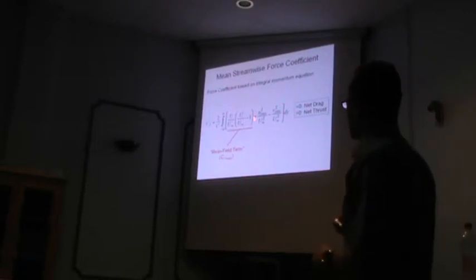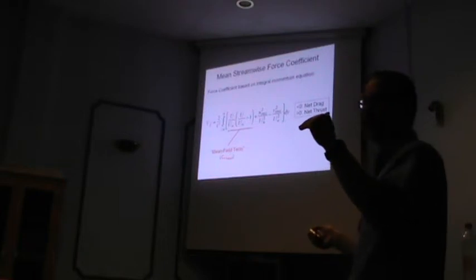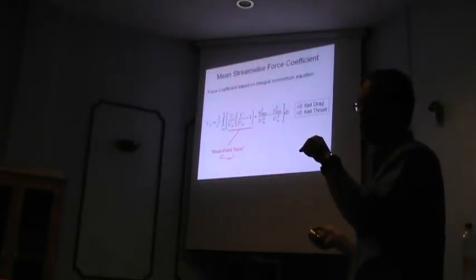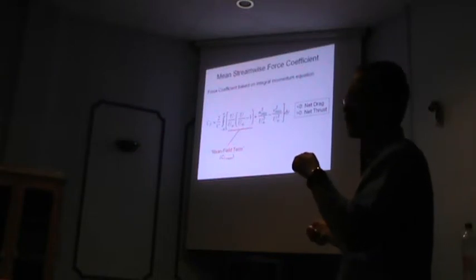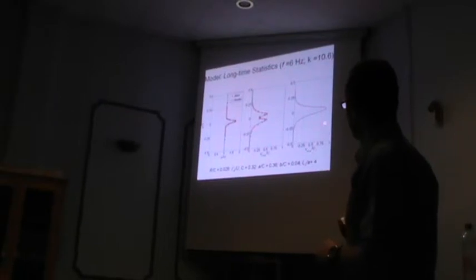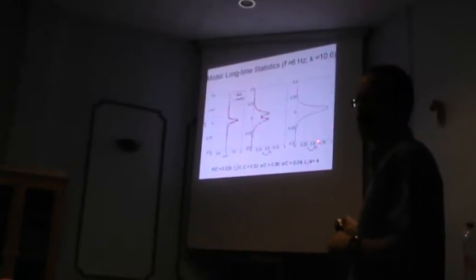Now, in many cases, you're not going to see these terms when people apply this equation. Part of the reason for this is that if the object is stationary, the RMS fluctuations are generally small compared to the mean velocity. Now, one thing I failed to mention is that if you look at these RMS levels, VRMS normalized by U infinity, you're actually approaching U infinity.